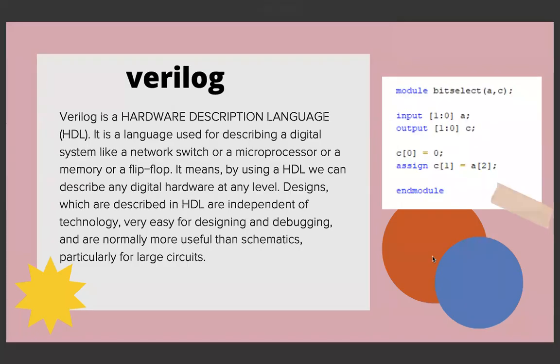So yeah, as I was describing, Verilog is the industry standard. It all starts with a module and ends with the endmodule. You declare the module name and have ports in it, input and output ports, and the operations or procedures are captured there. So that's what it is used for. Verilog is used for both design as well as verification, but using Verilog for verification is not very applicable because most of the things are not synthesized.